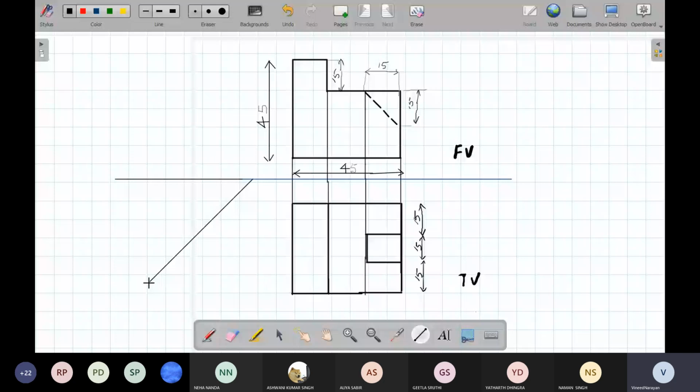Remember, these are thin lines which are called helping lines. So now I am extending this up to here. Same way, this edge also I can extend up to this. Now these two lines also I can extend. These are called projection lines or helping lines. They are thin because they are drawn only to make our drawing easier.